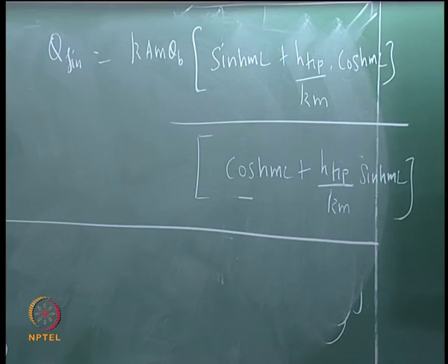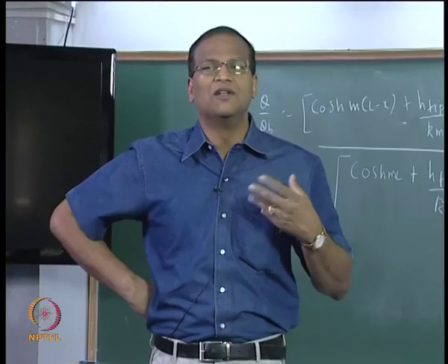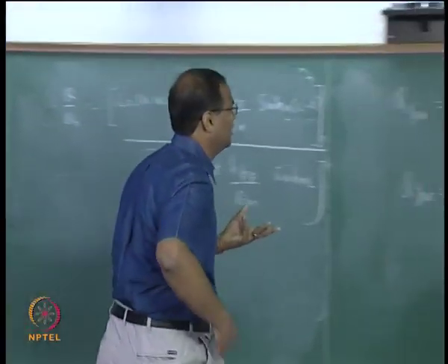Okay. So as the algebra gets tougher and it is almost about to consume you, I will give you some relief. For most practical cases, we can assume that the tip is adiabatic. We can substitute h tip equal to 0, okay, for the adiabatic fin.